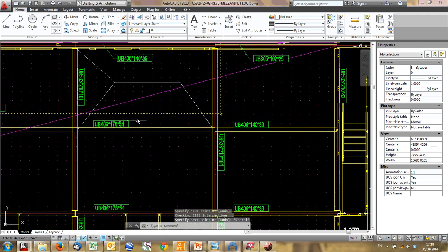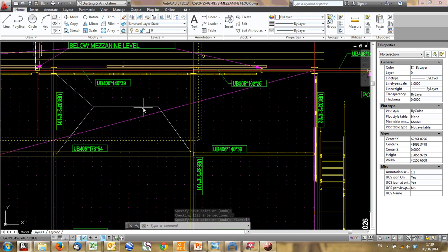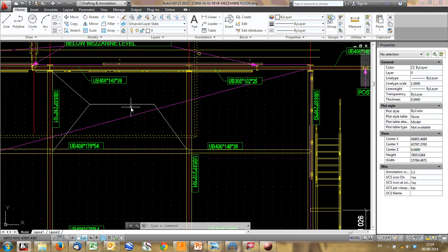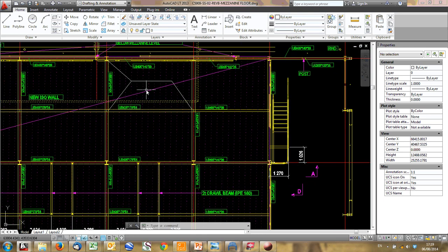The way I've drawn it is probably even correct, in that more load will be attracted to this side than that side because this is stiffer. So this is fixed-pinned because this concrete slab we're looking at is continuous this way. So 55-60% of the load will go here, where 40-45% of the load will go there. Alright, and you can then do the same thing. This just highlights how much load goes on each of these.